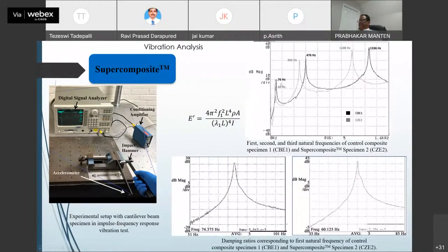So it shows that yes, the super composite laminate dropped in stiffness, but also the bandwidth increased for each of these modes. If you see in this example over here, you can take the resonant frequency and fit it into a differential equation and form a closed form solution. And these are all things which we record in my dissertation. These are out there in literature. All my papers describe how to get this.